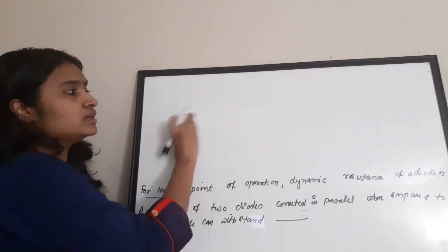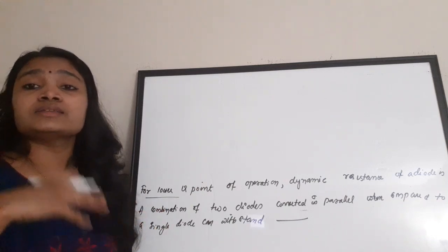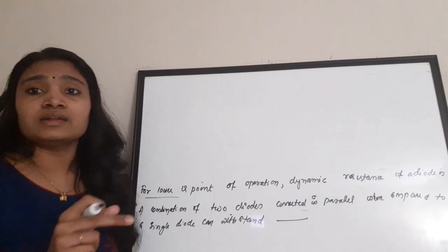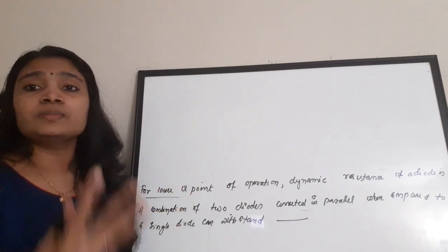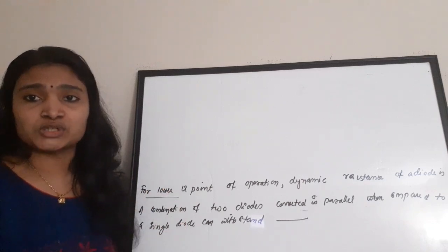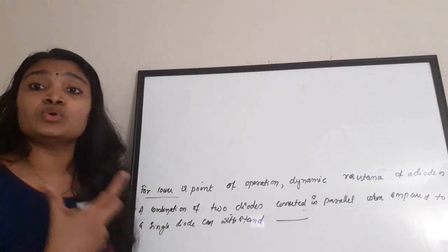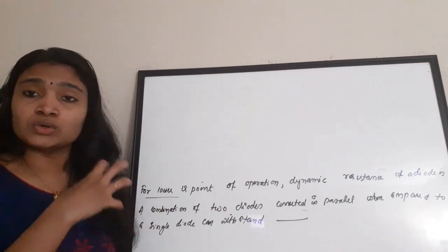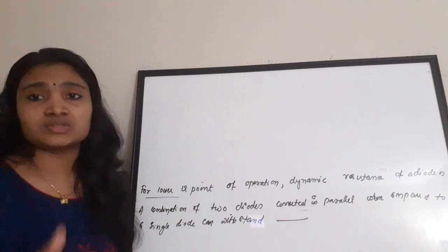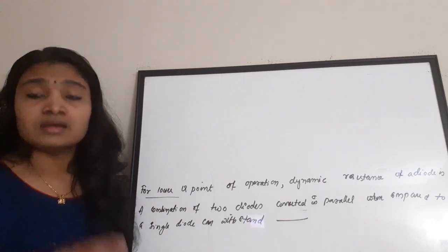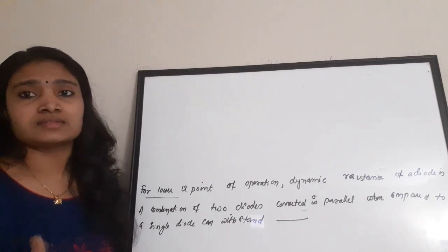So if the total current to be handled by the circuit is greater than the current rating of a single diode, we connect the diodes in parallel. When connected in parallel, this connection of diodes can withstand more forward current. So the answer is it can withstand twice the maximum amount of forward current. That is the correct answer.